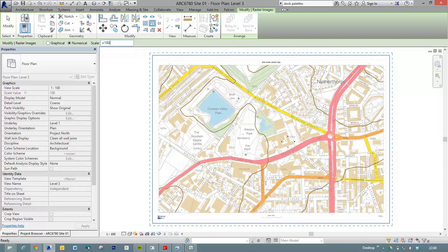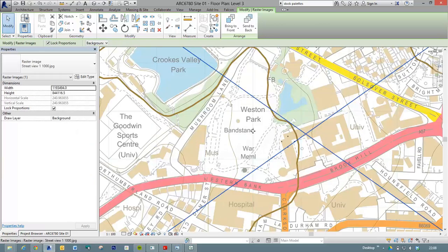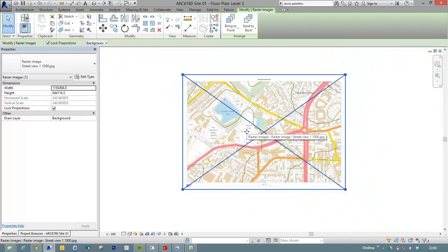And what I actually had measured off was 41.5 meters. So it will perform that scale factor, hit enter on that, which is about 2.4. And now it's prompting me again for the scaling point. Just click anywhere, I'm not too bothered there.